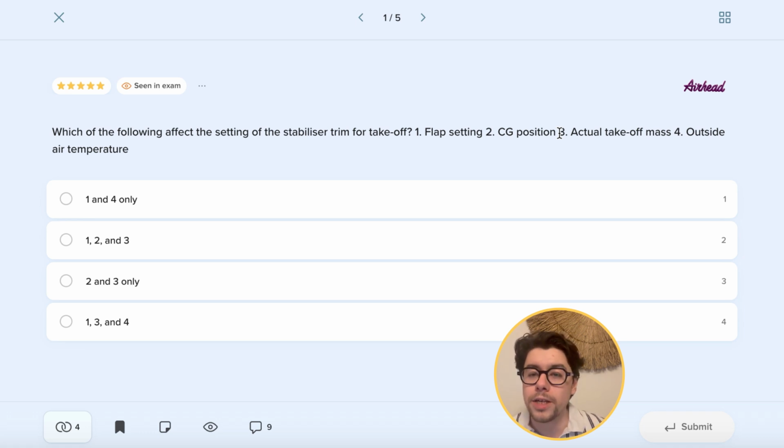Of course, it will change the thrust that the aircraft will generate. However, it is not that significant. And remember that in some aircraft, we will actually use flex takeoffs, where we will trick the engine into thinking that the temperature is different than it actually is. So temperatures come into play a lot there, and this would not really matter when it comes to the settings of the THS.